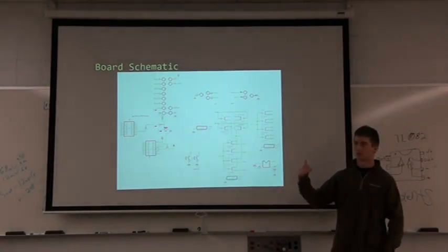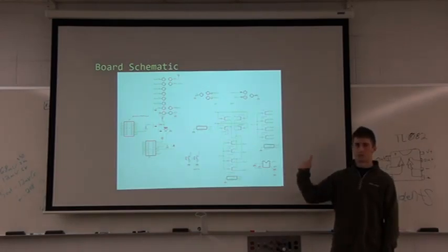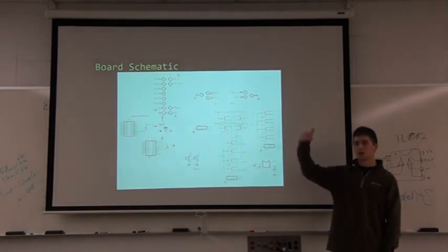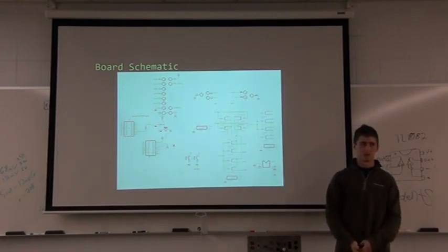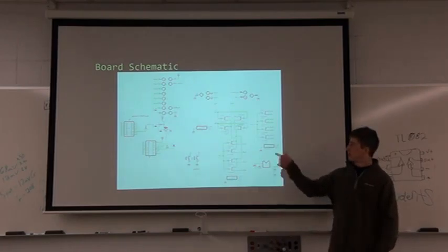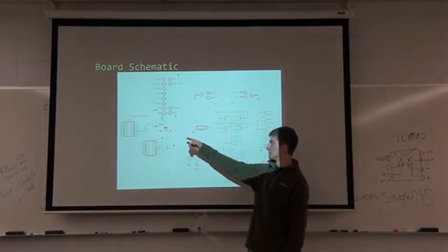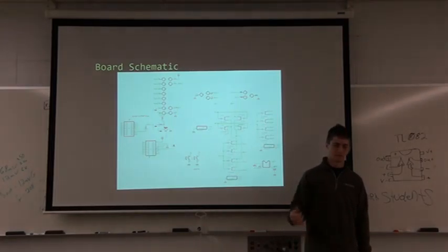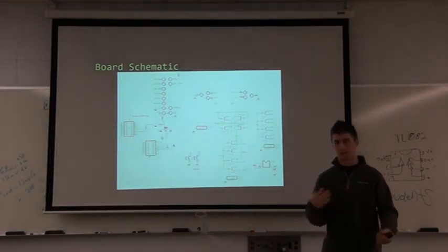My signals are going to be ranging from 100 millivolts peak to potentially at max 350 millivolts peak, and so that way that resistor just limits the amount of current that goes into the input of the comparator, so the diodes don't